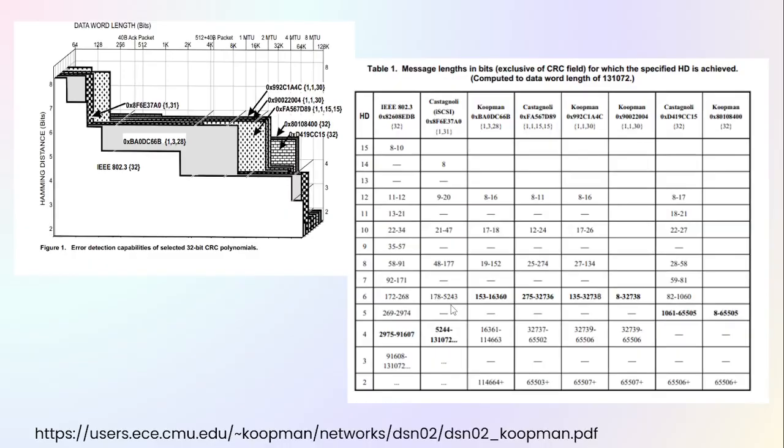Okay, now a quick word, some of you might be interested in thinking about the efficiency of CRC itself. So the CRC theory is based on what we call the Hamming distance. So picking a CRC equation and its efficiency depends on when you code a message with its CRC added, then what is the Hamming distance between code points, right?